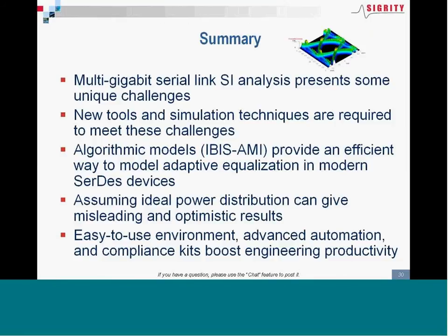Okay, so in summary, some of the different things that we covered today. Obviously, multi-gigabit serial link SI analysis presents some unique challenges. It becomes very difficult to cling to ways that you've done in the past using traditional circuit simulation, simply from a simulation capacity standpoint, as well as dealing with some of the adaptive equalization in the modern SerDes devices that you come across today. And this brings a look at new tools and simulation techniques, some of which we presented today.